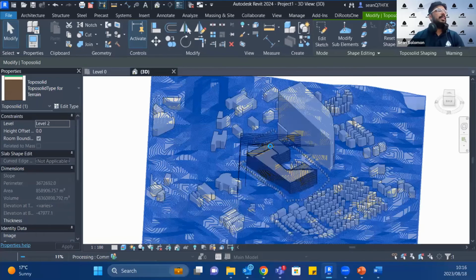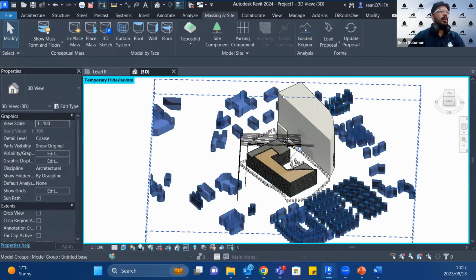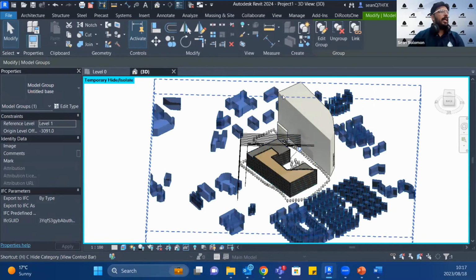The other thing I wanted to show you guys is that when you actually mark out the typologies, it makes internal walls as well, which is very nice. So it kind of gives you a very nice rudimentary design of the building. So if you were somebody that wanted to spend a lot of extra time actually developing it in Forma, you get a very good result when you take it to Revit. You don't have to worry about doing the work twice. But for the guys that just want high-level drawings, it works just as well.